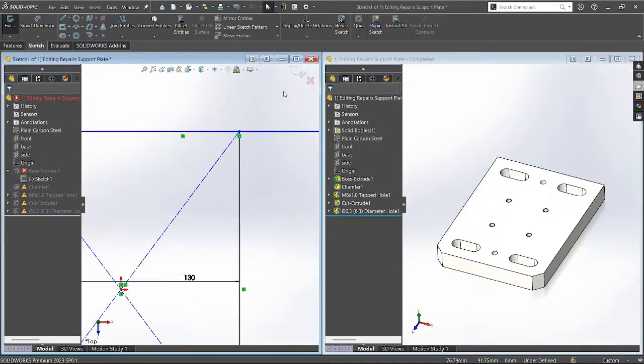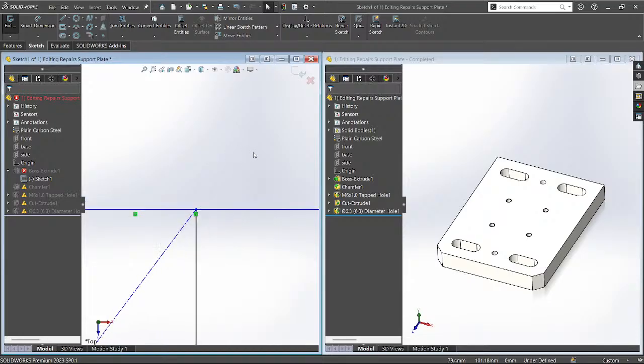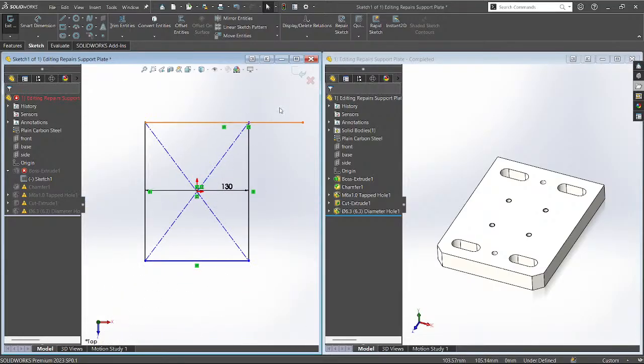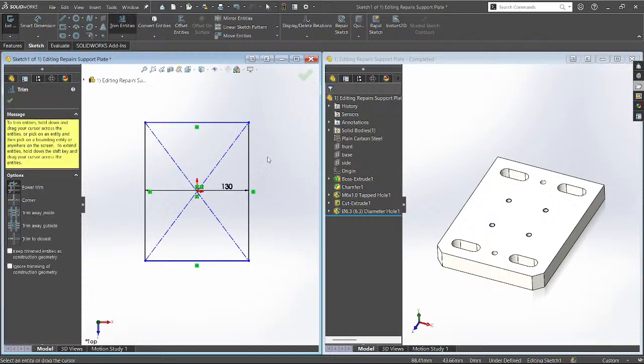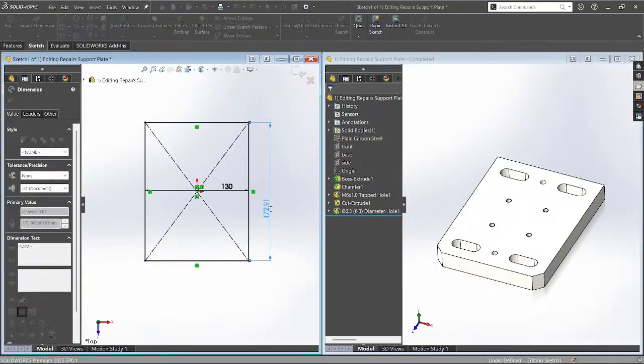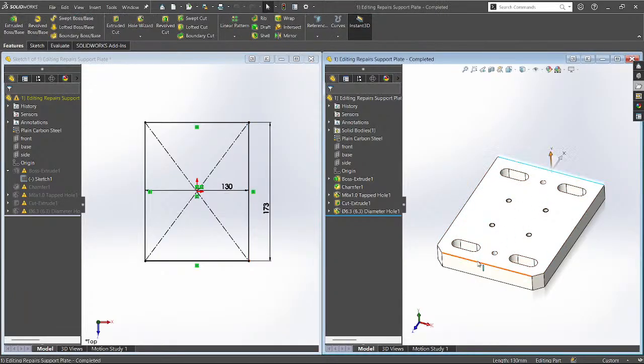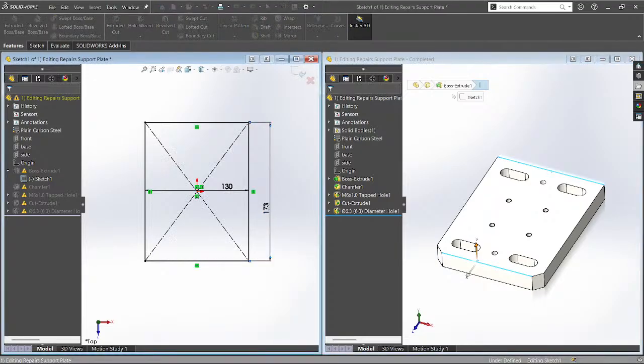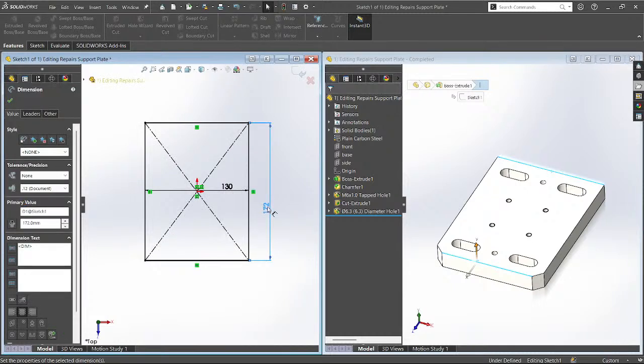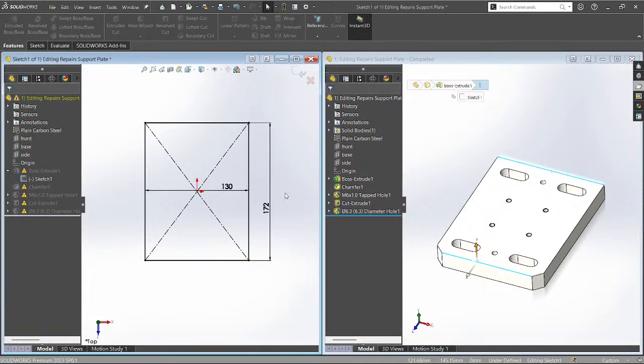And now if I just zoom in, still there is no issues. So I could see there is an extension here, right? I can simply remove this, and there's no dimension defined for this. What I can do is, let me just approximately measure. It shows 172.90. It might be 173. Let me just assign it at the moment. Just to make sure whether I'm right or not, I can use a shortcut. Hold the control, select these two edges, and automatically it shows the value here. Now the dimension is 172. In short, it should be 172, right? Yep, I'm done with this.